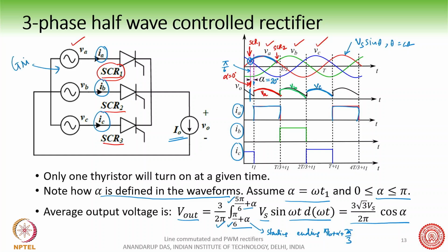This is the grid. And I have told you previously also, in the case of diode bridge rectifiers, this quasi square wave current which is drawn from the grid is very problematic for the grid. Grid does not like this. This is one of the biggest problems of thyristor rectifiers. We'll come to this.